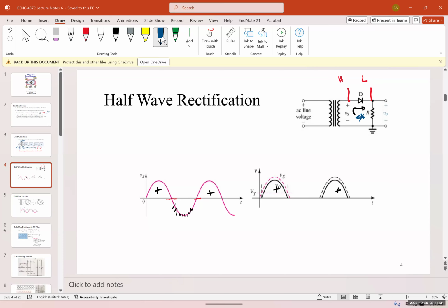In the real world, the efficiency of a half-wave rectifier is around 33, 34%. It's actually less than half because you have waste in the diode as well. Obviously, in the diode you have a forward voltage drop of around 0.7 volts, and that creates heat and waste in the system as well. So you're not going to have 50% of the power. It's closer to 34, 40%.